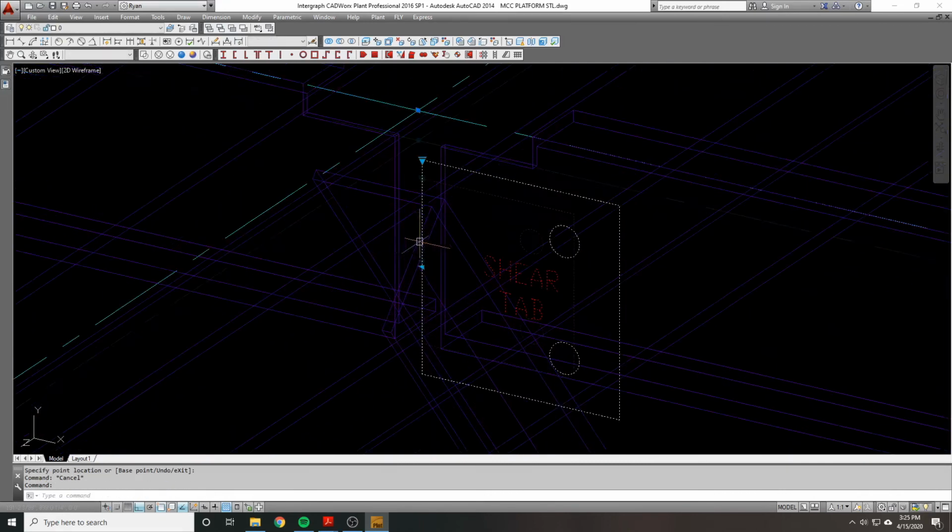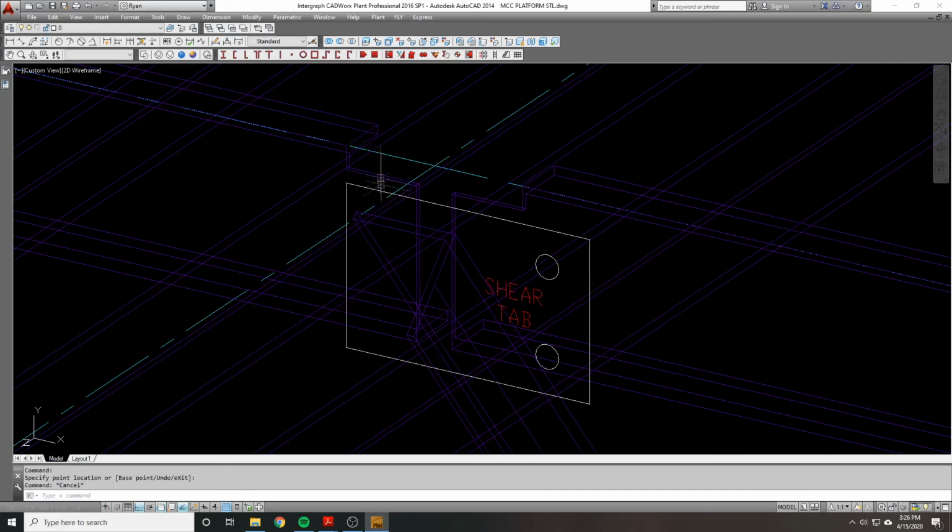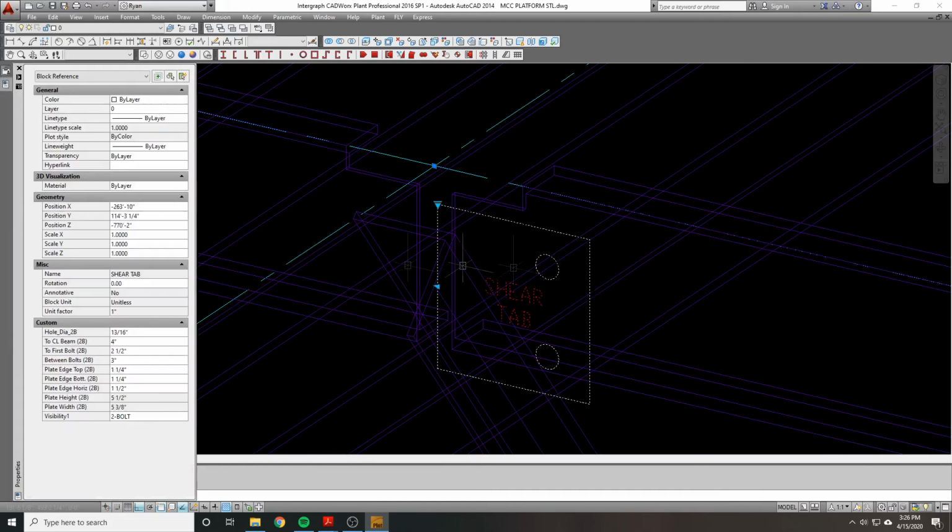That happens with stretch objects because they're locked to one direction. You can snap them to an adjacent object and they will still snap to that direction. I can click all the way over to here if I wanted to, and it'll line it up with that edge. So the rest of these properties are going to be in the properties menu. They're not controlled with the grips. I have the grips turned off because I want whoever's using this to control the dimensions. I've tried labeling these as succinctly as I can so that people understand what we're working with.